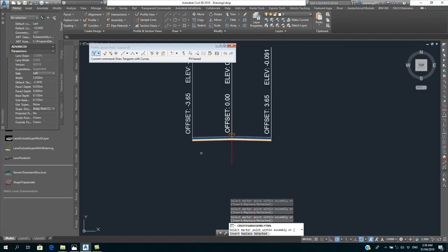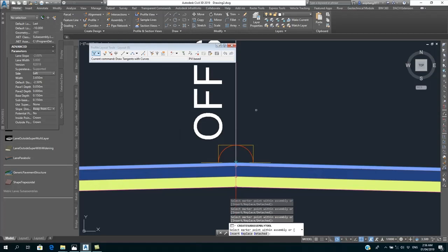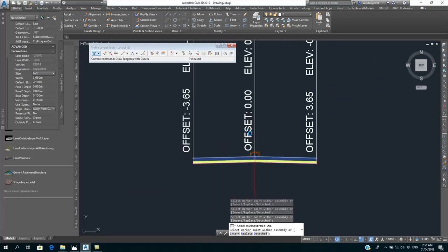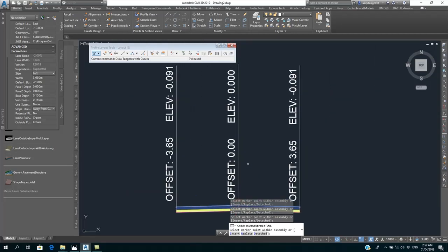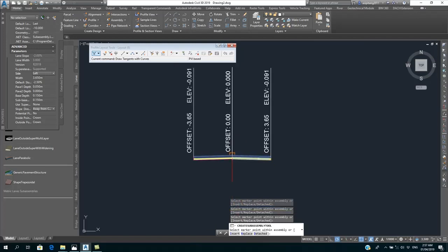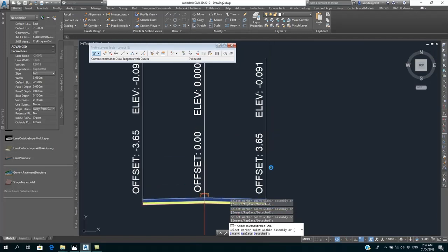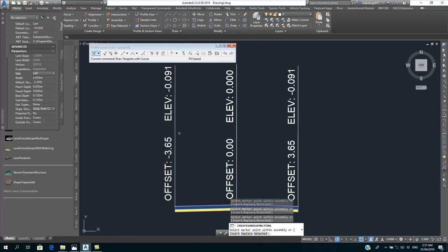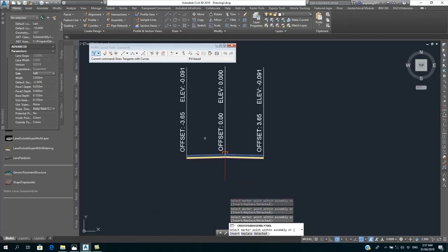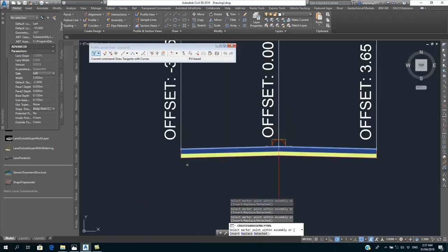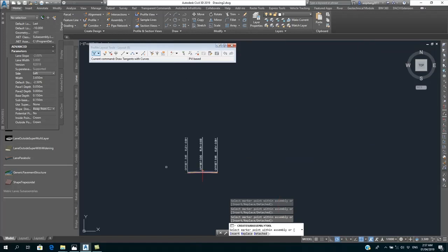You can see as I define it, it gives me the levels, the current position levels. But this has been detailed already because I'm using my existing template for the elevation at this, and also the extent of the offset, 3.65, and the elevations at that distance. So with this information, whatever I build out, the final information, the cross section intervals, will show those current levels. That's why I have it in my profile levels. I can also have it in the cross sectional levels with respect to the cut and fill information. I think before we finish this, we'll see the trend of what I'm saying.